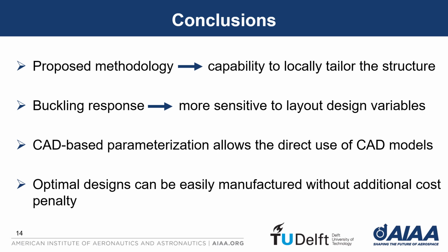Conclusions. The proposed methodology successfully performs simultaneous size, layout, and topology optimization. This provides additional capability to locally tailor the structure. The buckling response of the stiffened panel is found more sensitive to the layout design variable in comparison to the size and topology design variable when optimized simultaneously.